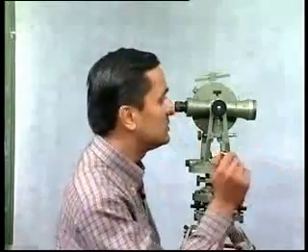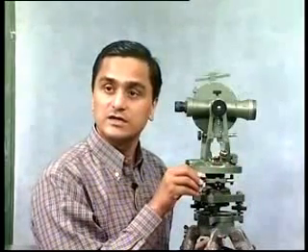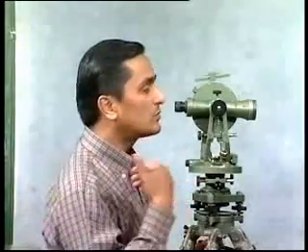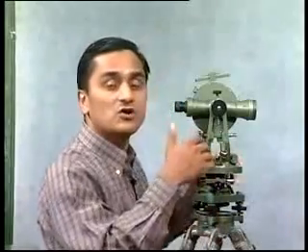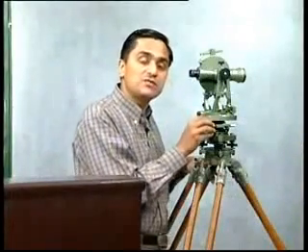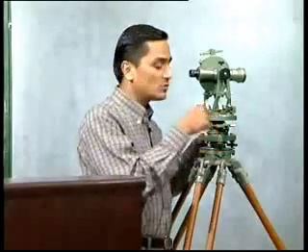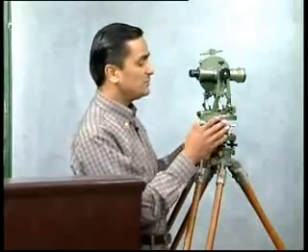It might happen, because I am looking through the theodolite, that by accident I touch the tangent. If this happens, the angle value will change. So while we are looking through the eyepiece, engrossed in our work, just by moving our hands here and here, by feeling these different millings of the screws, it is possible to work without looking at these screws. This is why the milling is different.